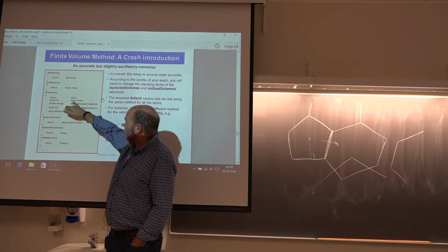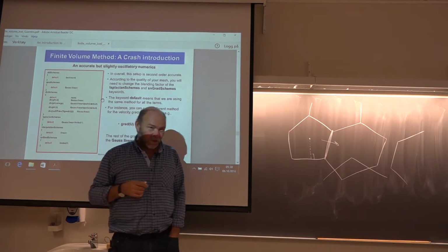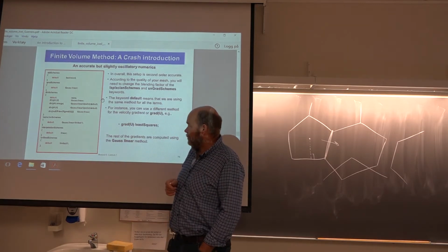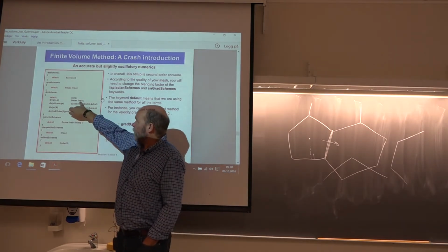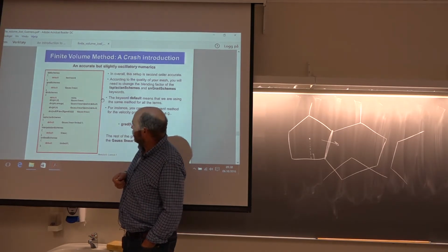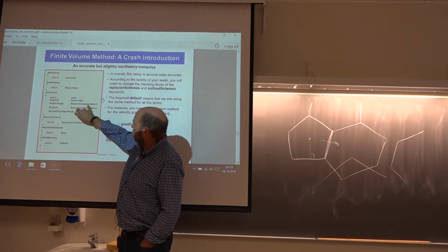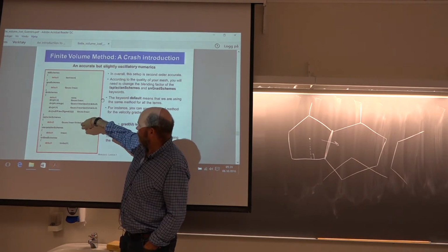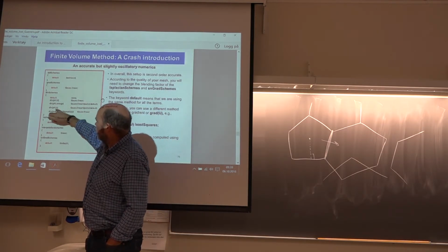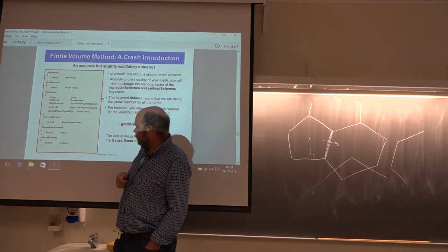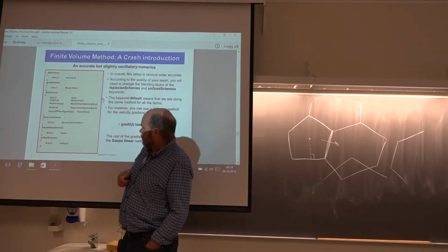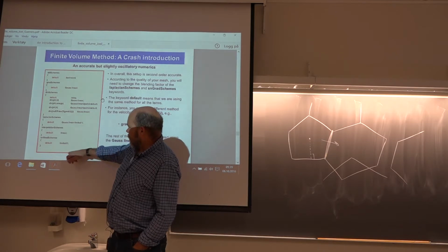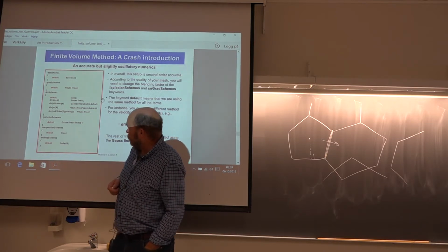Here it says Gauss linear, that's second order, but the central scheme, very jumpy, we know that. And here linear upwind default should be okay, I think, for these. That's k-omega, so yes, it's a turbulent case he's running here. And the rest just the standard linear, yes.